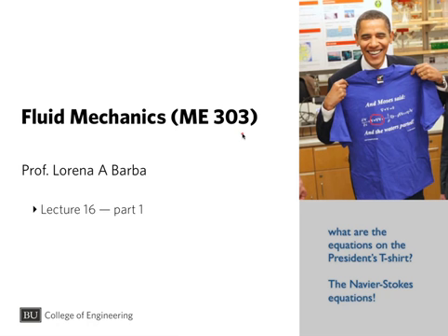For linear partial differential equations, we can use the principle of superposition. And the principle of superposition allows you to find solutions in many, many complicated situations. But for nonlinear equations, we can't use that. There is no general method that we can use for nonlinear PDEs. So that's a term that causes a lot of trouble in both the Euler and the Navier-Stokes equations. But for creeping flow, that term can be neglected. Basically, inertia terms can be neglected. That term is related to inertia. And the flow is completely dominated by viscous effects.